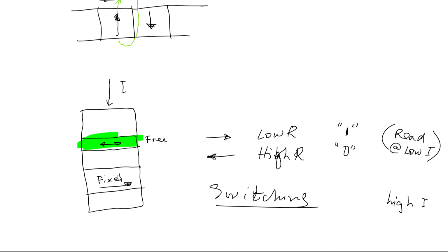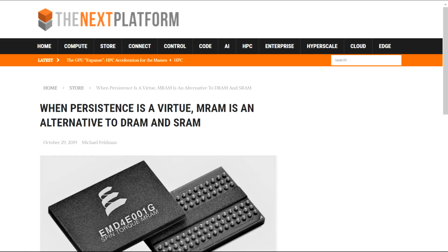So if you have electrons flowing this way, you'll apply torque from the fixed layer. If you drive current in the opposite way, you will switch by the reflected electrons from the fixed layer. So you either switch it one direction or the other direction. So what it allows to do is to implement a memory which does not require separate contacts to write and read information.